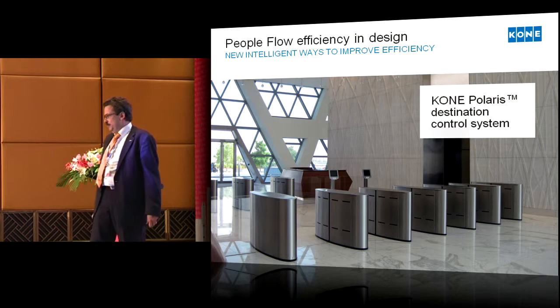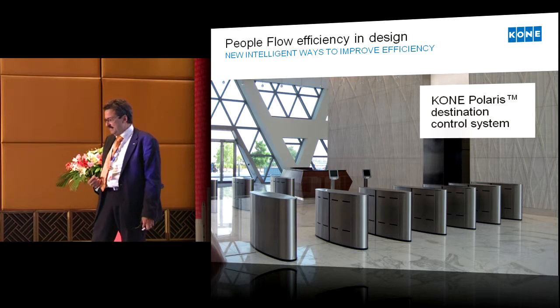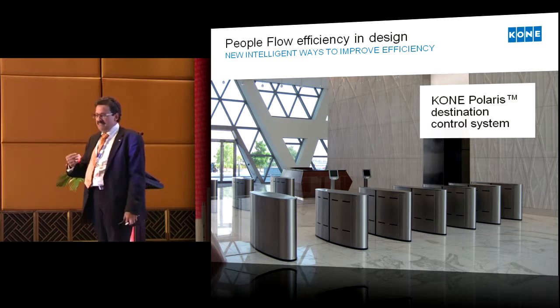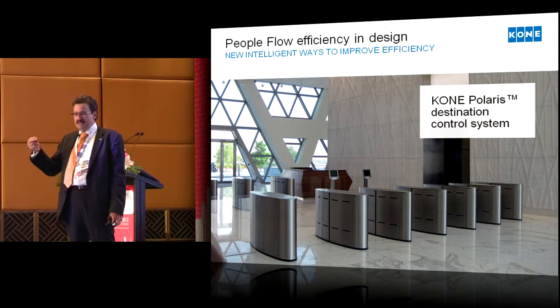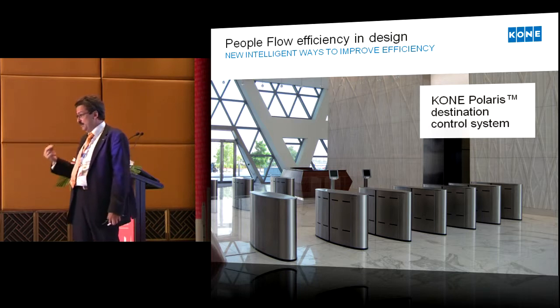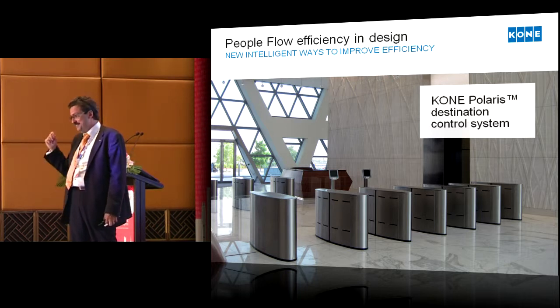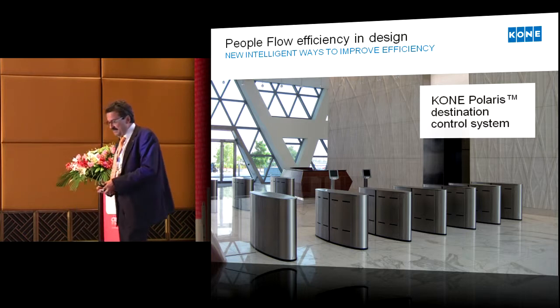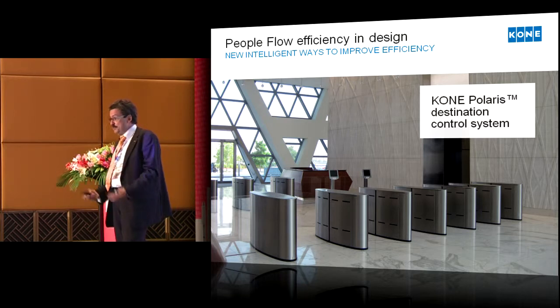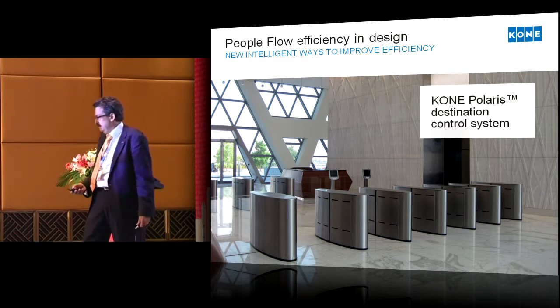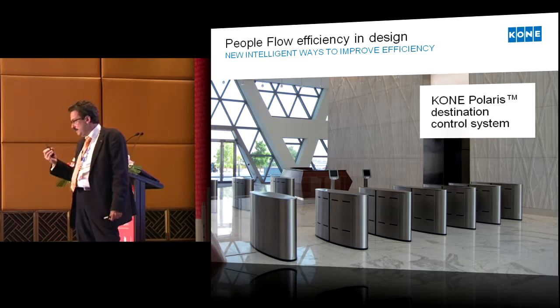Then we go to the intelligent way of adding efficiency. And that is whole call dispatching, adding more intelligence, getting more information before you enter the elevator, so getting information already outside the elevator on where you want to go, instead of first when the elevator arrives inside the elevator car. So these whole call systems have dramatically improved the efficiency of elevating and therefore reduce the core and give us more chance to get that 50% extra efficiency which we really need to be able to keep the carbon factor down.